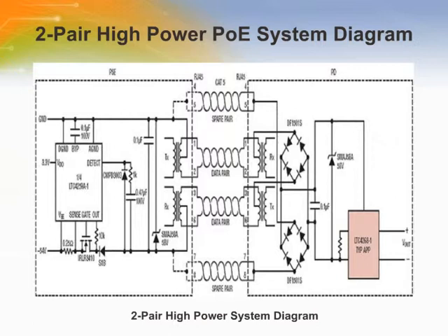As shown on the block diagram, 2-pair power is used in today's 802.3 AF systems. 1 pair of conductors is used to deliver the current, and a second pair is used for the return while 2 conductor pairs are not powered. This architecture offers the simplest implementation method, but suffers from higher cable loss than an equivalent 4-pair system.